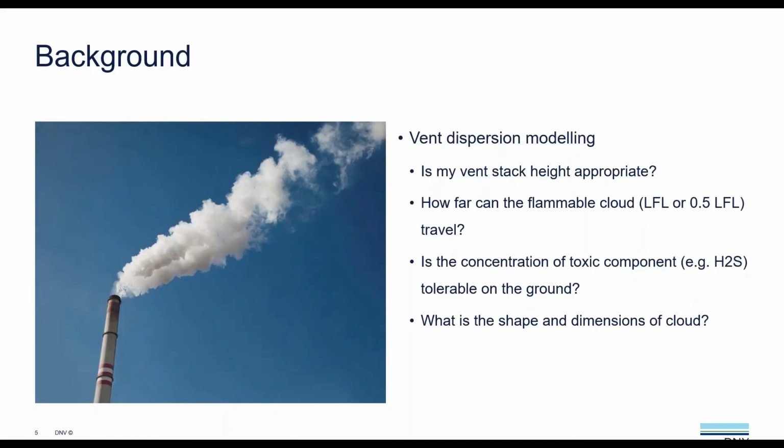So here is a slide on the background of vent dispersion modeling. Venting is a widely used method for disposal of unwanted gases which are produced in the process industries. In order to ensure that the hazard from the venting is safe to the people located nearby, we then have to look at whether my vent stack height is appropriate or not.